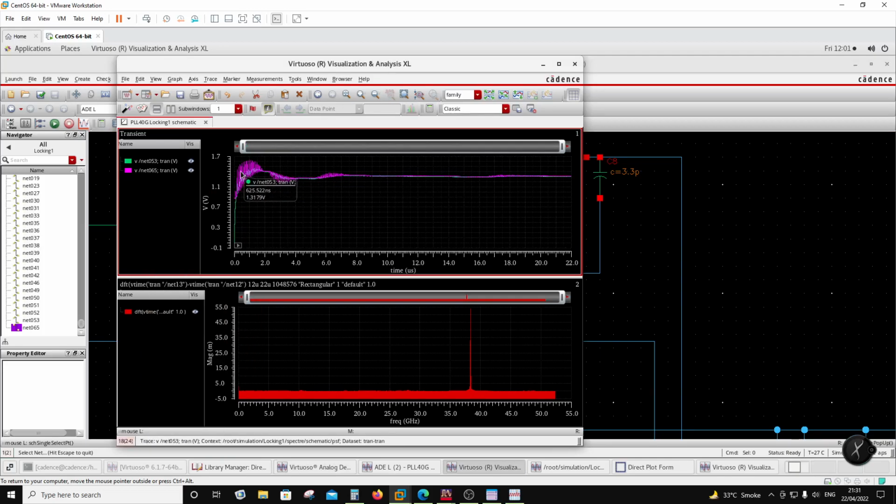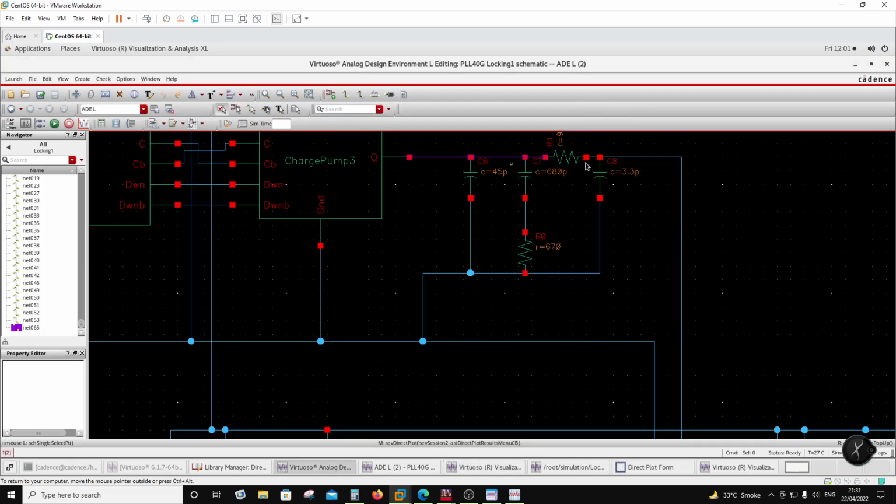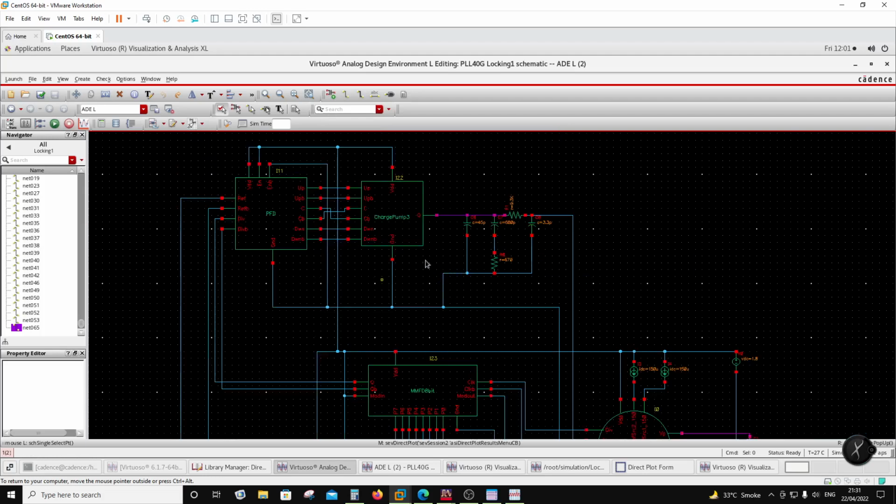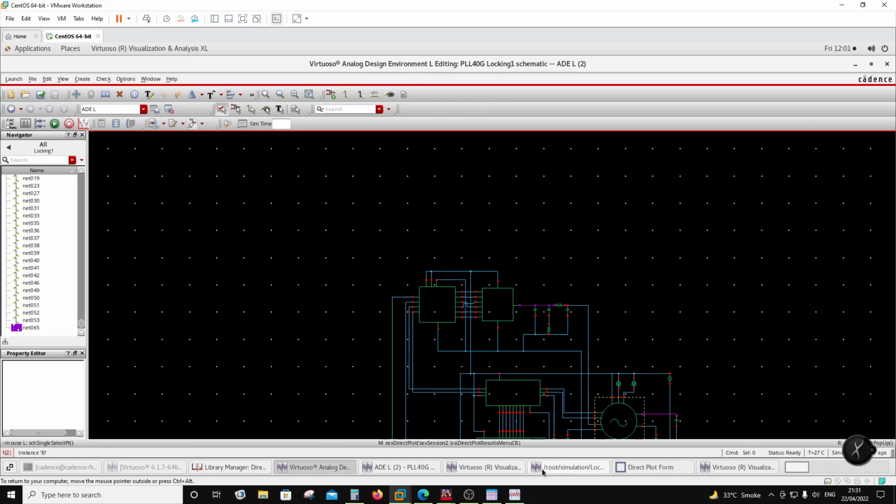Okay, so when you start seeing these spikes die out, right? And then the magenta basically follows the green, which means that there is no current in the loop filter, which means all the caps have reached their final value of voltage, right? That's basically where the locking is exact, based on the fraction. But anyways, what I was trying to show here is that.